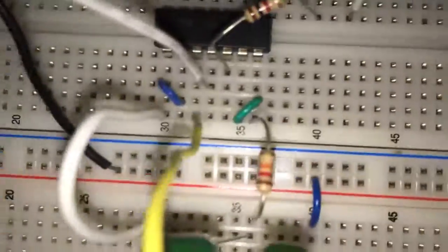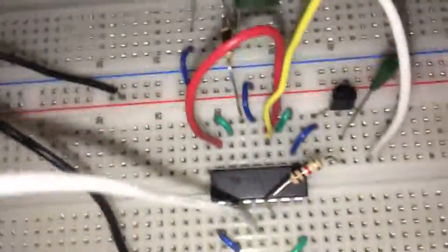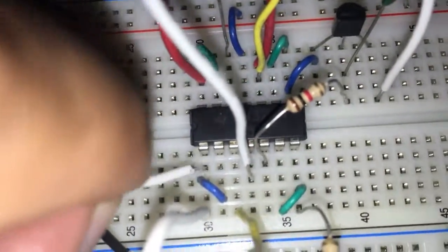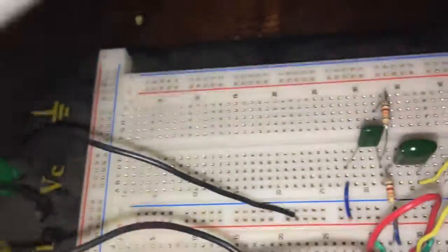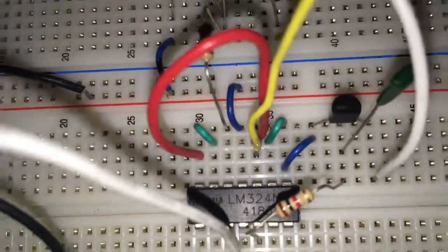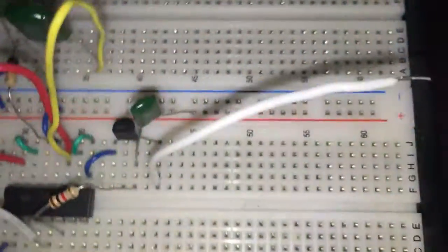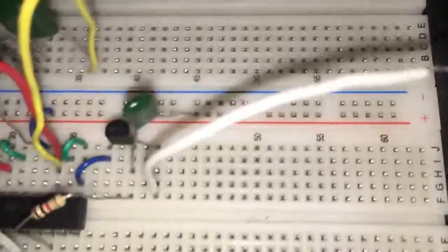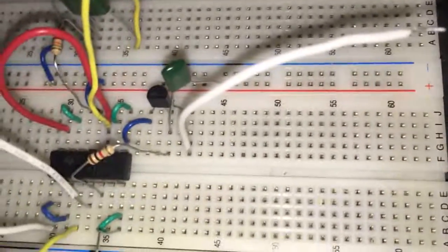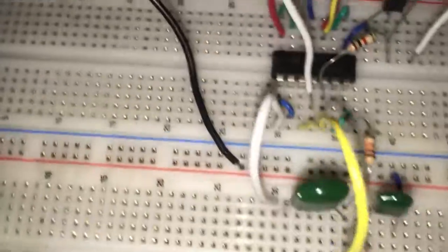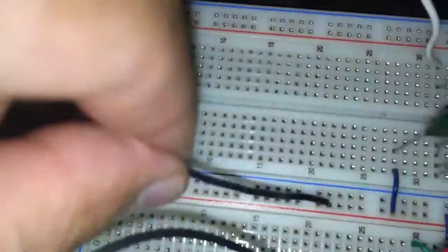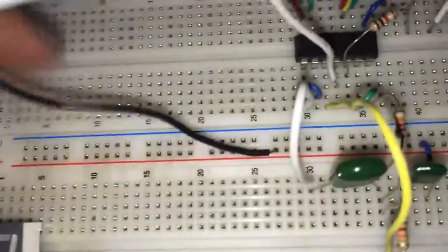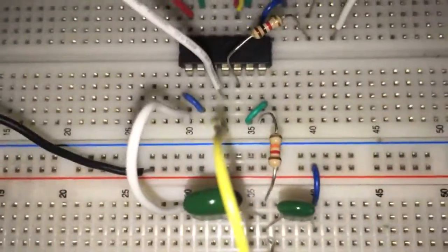We will collect our output from a wire similar to the one I have here. For the sake of showing you, I will put it here, and that would be our output. We just connect this to our oscilloscope and get a reading. This wire here is connected to our power source, which can generate a pulse, and our ground wires. Our ground wire here is connected to the red line there, and the ground wire here is connected to that line there, and that's about it.